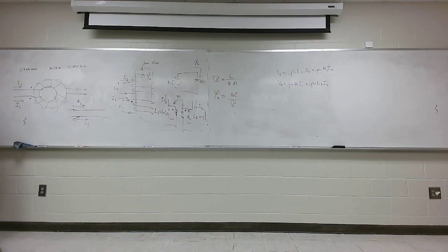Do you all follow me on this? This is real important. Some people don't know that. Forget about the voltage. The current is the thing that's so important. So in a coaxial cable, regardless of the frequency, the outer rim, that foil, will carry some current I. The exact same amount of current. If you cut that thing and look at the time signature of the current, the same magnitude, opposite direction current will flow in the core. There's no time phase difference. Y'all follow me on that?